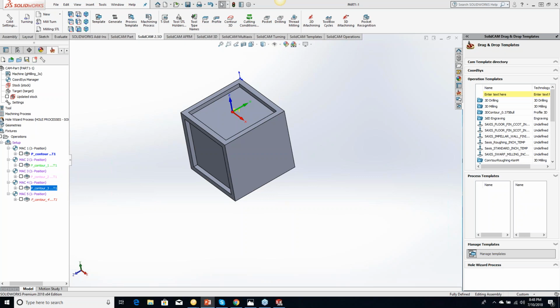How you can do multiple tools in one operation is a really cool one. So if you're roughing and then finishing, you can actually use 2 tools all in one operation now without having to do a save and copy and switch out the tools. So really cool stuff coming for next week.